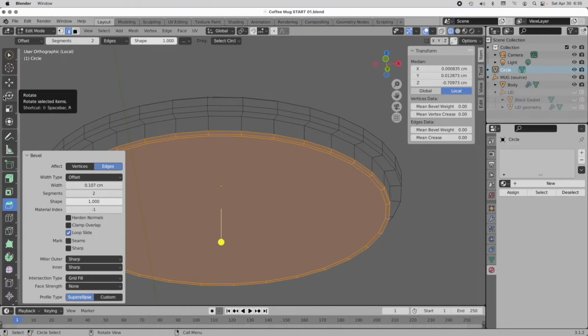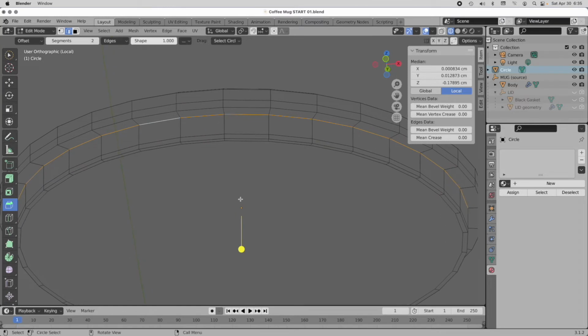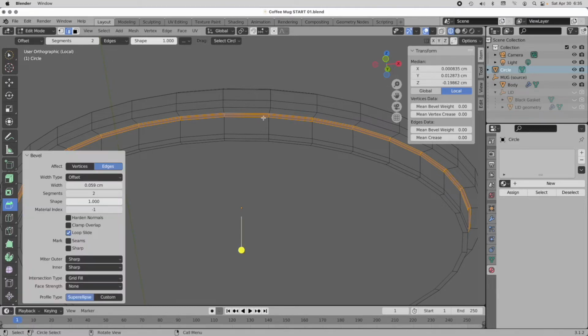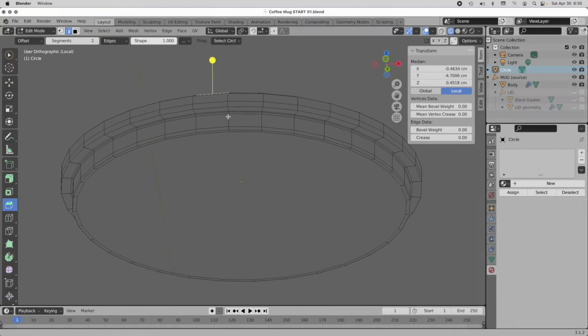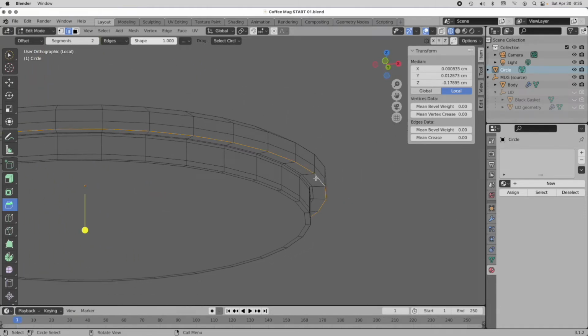Okay, the next thing that I'm going to do is I'm going to double-click this edge. I'm in edge mode, and I'm going to do the same thing. I'm going to come over here and I'm going to produce a new set of bounding polygons on either side of that edge, which is going to constrain it, make it a tight curve right there. And then we're going to do the same thing here. I'm going to double click here.